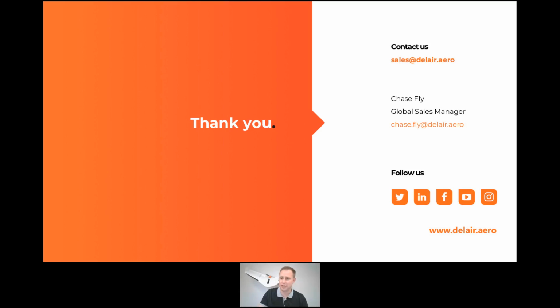Joshua Hawley, you asked, will the ADS-B out meet the remote ID requirements for beyond visual line of sight in the US? I would love to just outright say yes, but a couple things there. Those requirements are not, to my knowledge, fully set in stone yet for beyond visual line of sight. Now they have released some rules, some standards, I believe, just recently for flying over people and over property that don't explicitly state ADS-B to my knowledge. However, I do know some of the exemptions that have been granted for BVLOS flights in the US have required ADS-B.